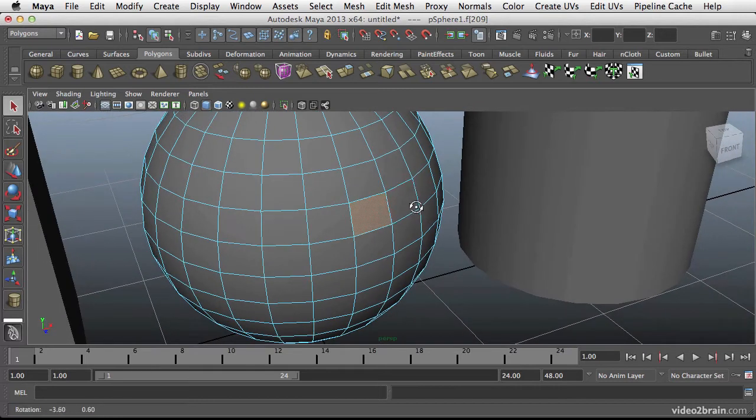And there are three main editing tools that you'll use continuously. They are located on the left-hand side of the screen. They are Move, Rotate, and Scale. And they're also hooked to three hotkeys, and those are W, E, and R. So you can see my tool handles switch depending on the one that I choose. So W is the Move tool. It allows you to move the selected polygons in any direction along the X, Y, or Z axis.